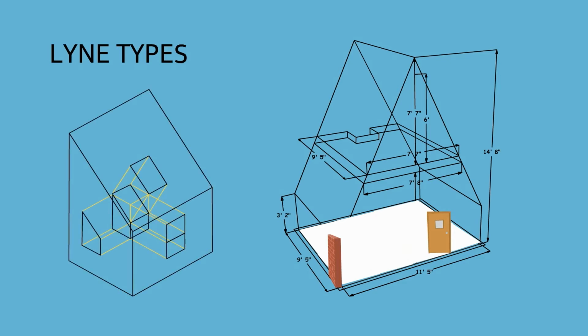Hidden lines are used to represent surfaces that are not directly visible in the orthographic view. Without hidden lines, all information about the features that are not directly visible will be lost. Whenever possible, show intersections and corners of hidden lines as touching lines, no gaps. There should be a gap at the transition between line types so that it is clear where one line type starts and the other one ends.